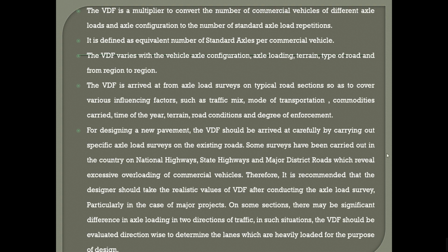Some surveys carried out in the country on national highways, state highways, and major district roads reveal excessive overloading of commercial vehicles. Therefore, it is recommended that the designer should take a realistic value of VDF after conducting the axle load survey, particularly in the case of major projects.